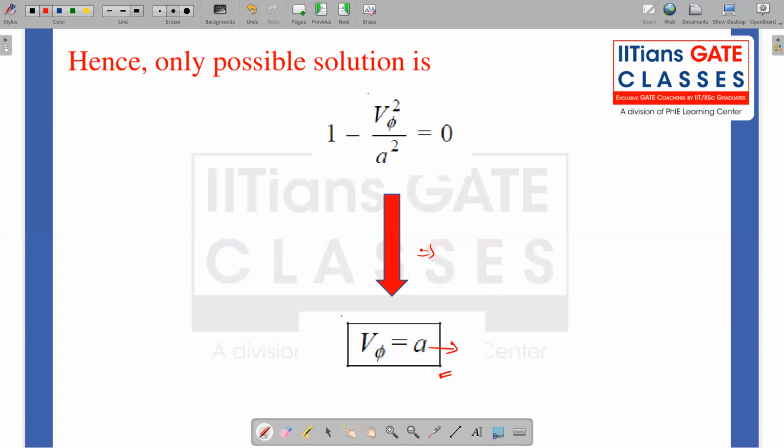So you also have to remember this Prandtl-Meyer function is basically derived based on the assumption that the property change in a supersonic flow happens across a gradual change. So irrespective of whether we are doing a diverging kind of surface, or the flow is seeing a compression corner, even a gradual compression corner.